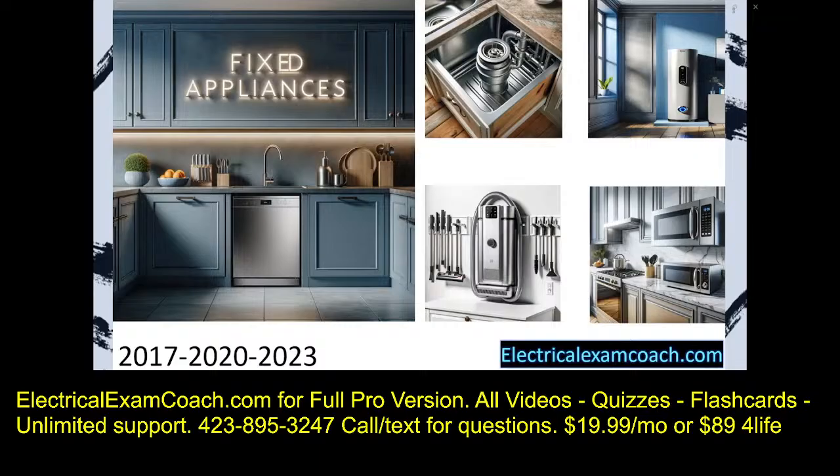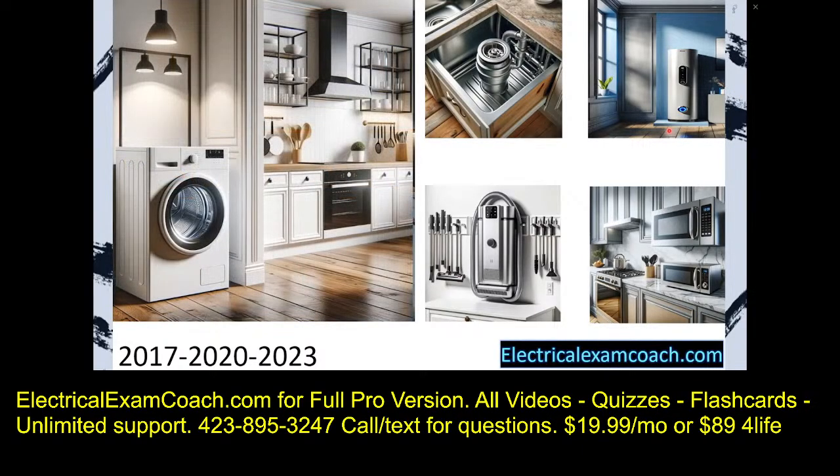You'll notice in this bottom right-hand picture that there's 2 microwaves. One is not fixed, and the other one is fixed. And when you fix it to the wall or fix it so it can't move, either with plumbing or mechanical vents or anything else, it now becomes a fixed appliance, and there's a special way that they calculate them when doing a whole home load calculation. What it does not include is dryers or ranges. We're actually going to deal with those separately. So this includes all other fixed appliances except for dryers and ranges.